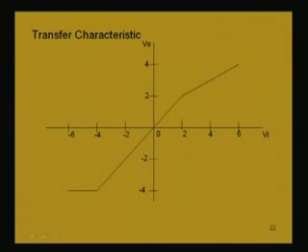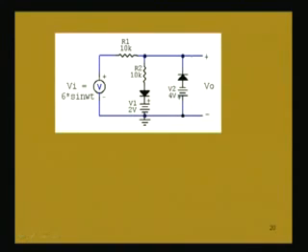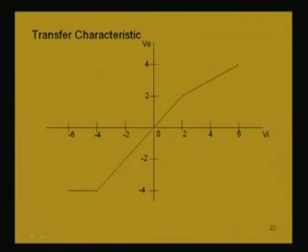the diode D2 is not conducting. When the diode D2 is not conducting, these 2 points are the same as these 2 points, since there is no drop, there is no current. When the diode D2 is not conducting in a negative half cycle, it cannot conduct because it is already reverse biased by this, and in the negative half cycle again it will be reverse biased, P will be connected to N. So, we get input and output voltage the same for this portion,